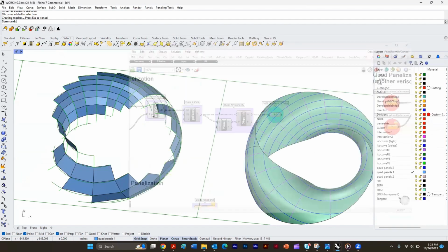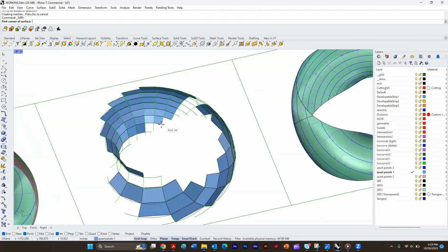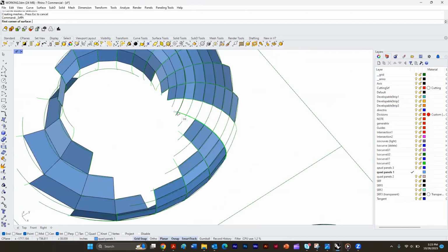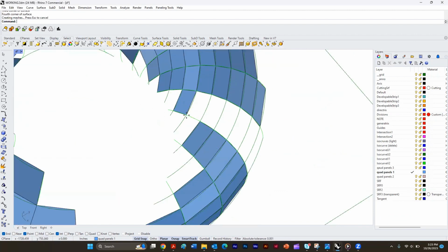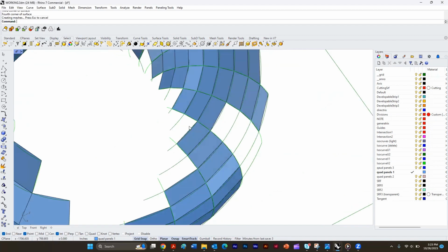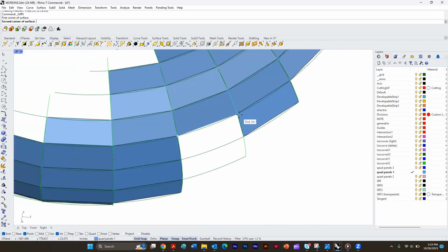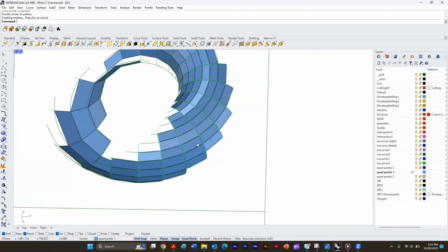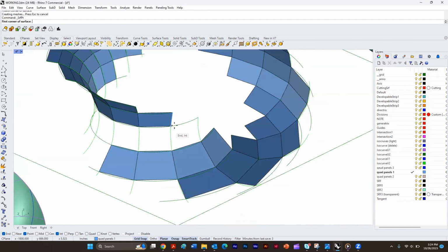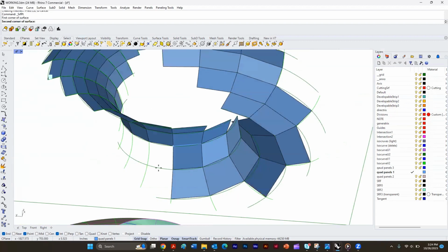And then you can close this, go over here, and it did not complete the rows, the start and the end, because I didn't write the script to do closed shapes. So the first and the last row are not being closed. So this last part you can do manually. You can go point, point, point, point. You have to be careful not to miss a point, because otherwise it ends up not planar. Here we go.